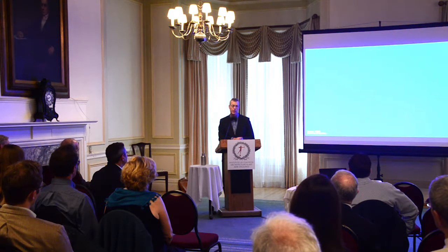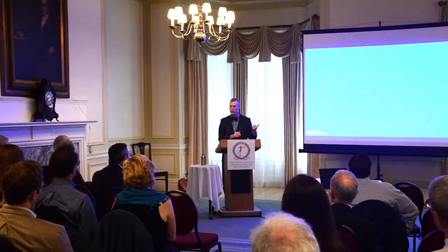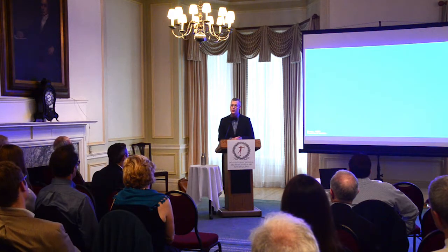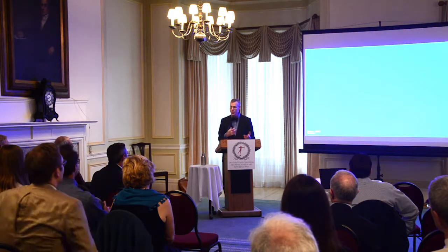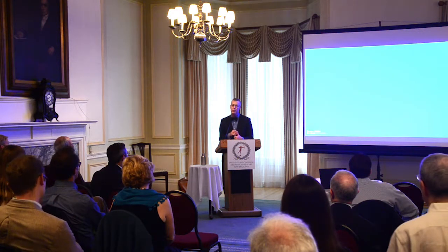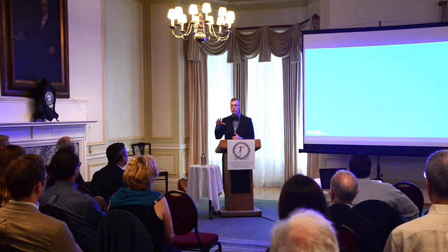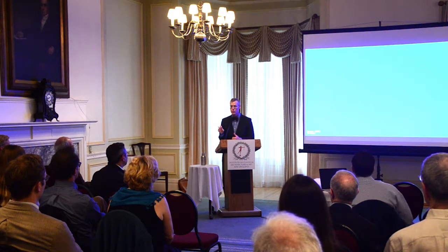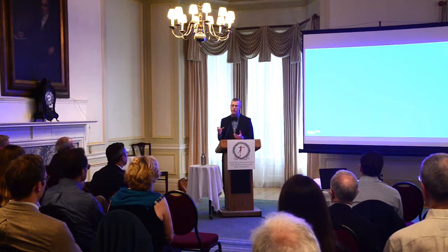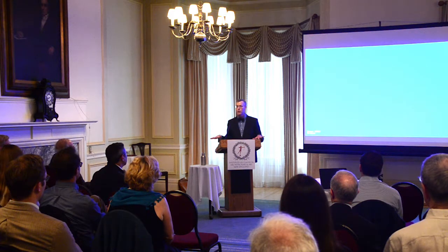that same ingredient. I think two things they did really well that are why we have 2,000-year-old concrete buildings like the Pantheon, and we're having mid-century 1960s buildings with a lot of concrete deterioration, is they realized, and we realize today, but we have a tough time getting it or enforcing it, is that when you keep the water to cement ratio low, all kinds of good things happen. The concrete's a lot stronger, it's a lot more durable, it's less porous, it's less absorptive. All those things are great for durability.